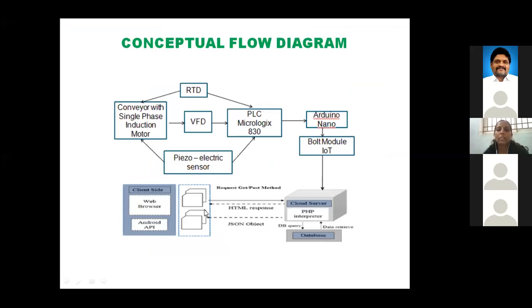So this is simply the same thing. Once you understand the basics of how the data is generated, all the case studies will look the same, with sensor parameters like temperature. Here, from the motor, we are going to measure first the temperature and second the vibration. The motor has stator and rotor coils, and inside them we are going to place many temperature sensors, and then we are going to measure the vibration also.